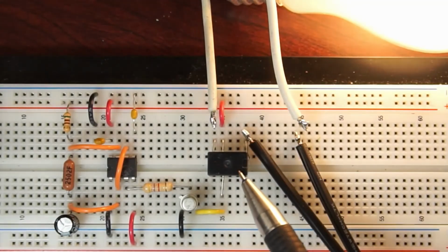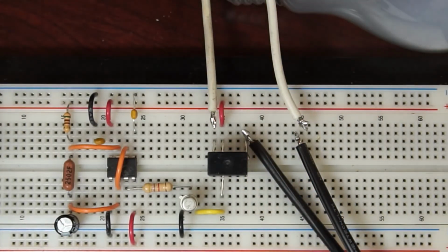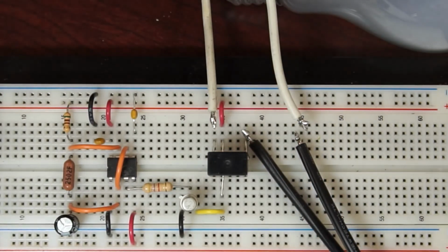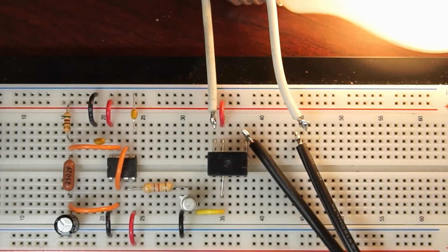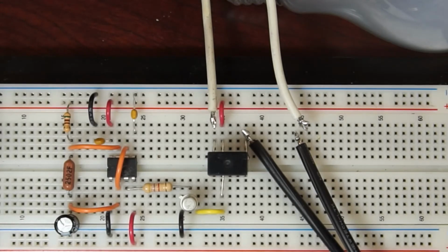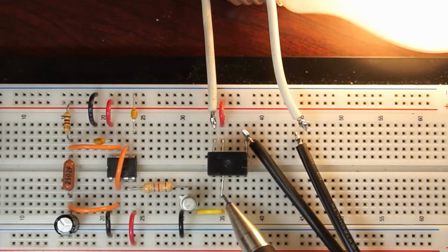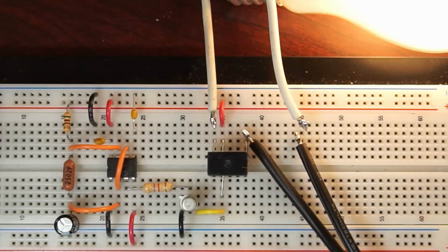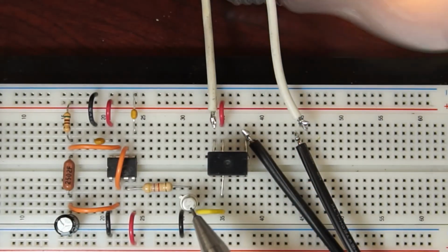This is the relay. It has 6 pins, but they're not arranged in the same 1/10 of an inch square grid as the holes in the breadboard, so I've had to solder short extension wires on in order to insert the relay into the breadboard.